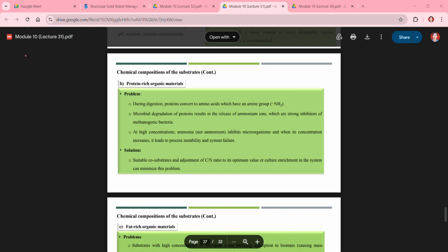What is converted to peptides in the hydrolysis process of anaerobic digestion? Polysaccharides, proteins, fats or fatty acids. So during the hydrolysis process, generally the protein is responsible for the conversion to peptides. The polysaccharides will go into the form of cellulose and hemicellulose, then again into glucose. Fats or fatty acids will result in the formation of more ammonia due to the higher nitrogen content. So during the hydrolysis process, the protein is converted into peptides, and these peptides are converted into butyric, acetic or propionic acid during the acidogenesis process.